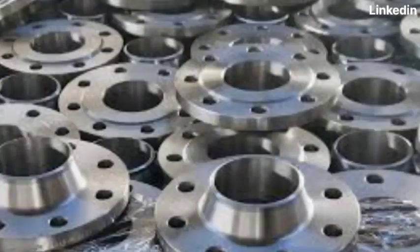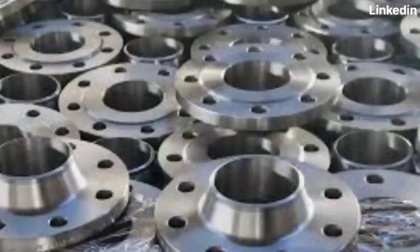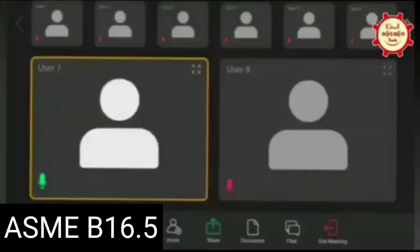My question is that those flanges, as far as I have checked, are not passing in PCC-1 Appendix O. There is a criterion in UG-44(b)(3) that the flanges should have the assembly bolt load as per PCC-1 Non-mandatory Appendix O. But the standard B16.5 flanges do not satisfy that criterion. They are failing. So how are others mitigating that issue?